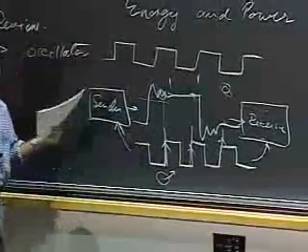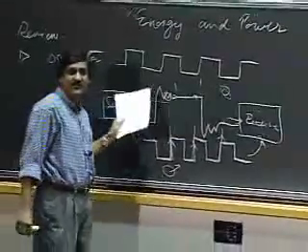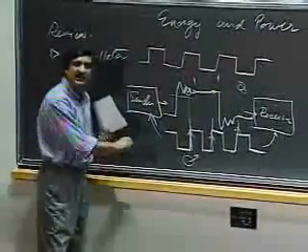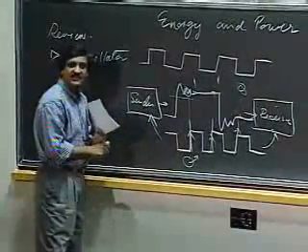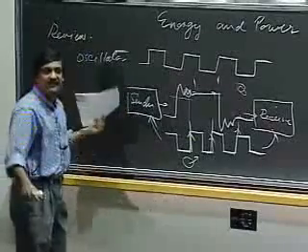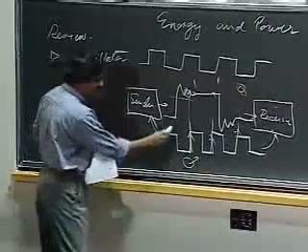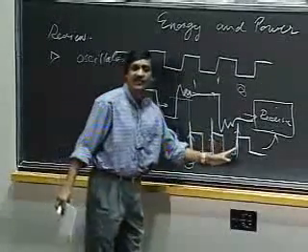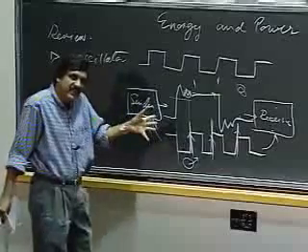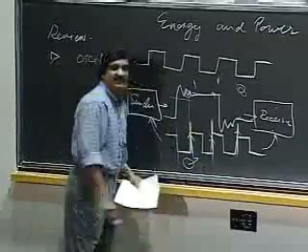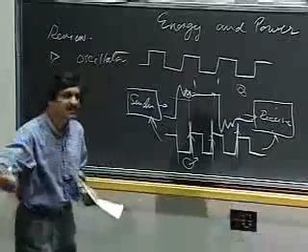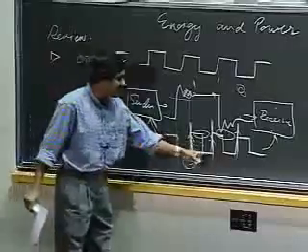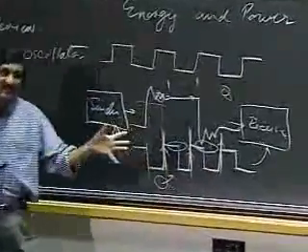What I'm saying is that, look, in the digital domain, we've already discretized value into zeros and ones. But we still had continuous time until now. And what we do in digital systems is to say, let's discretize everything, and let's discretize time as well into these points that happen on the rising edge of the clock, which means that the circuit has meaning, signals have meaning only when the clock is rising. That tends to discretize time, which means that I really don't care what happens to signals in this time, as long as on the rising edge of the clock, I get the right value.